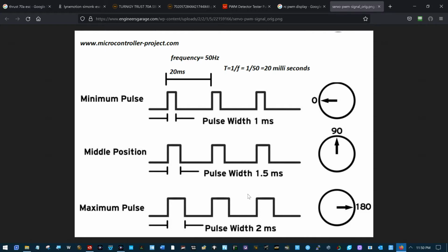They also sell that same resistor with a tolerance of 10%. Those are a little more expensive for that 100 ohm resistor, and it's guaranteed to be within 90 ohms and 110 ohms. They sell them down to plus or minus 2%. That resistor will be from 98 to 102 ohms when it's marked as 100.